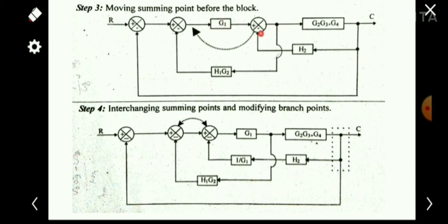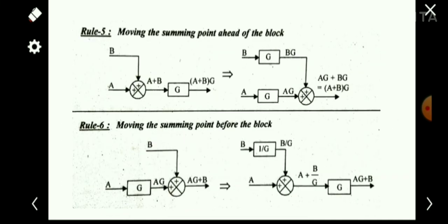So this summing point will come here. For moving a summing point before this G1, we have to look at the rules. If you are moving a summing point before a block G, we have to add a 1 by G in this line, in the line B.